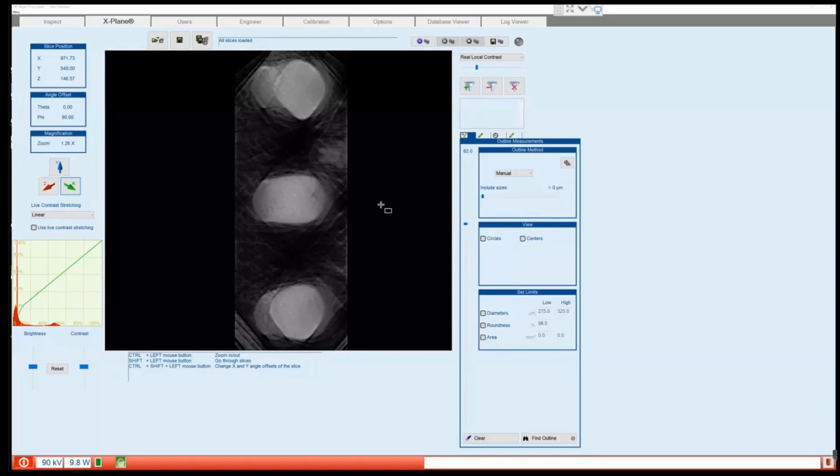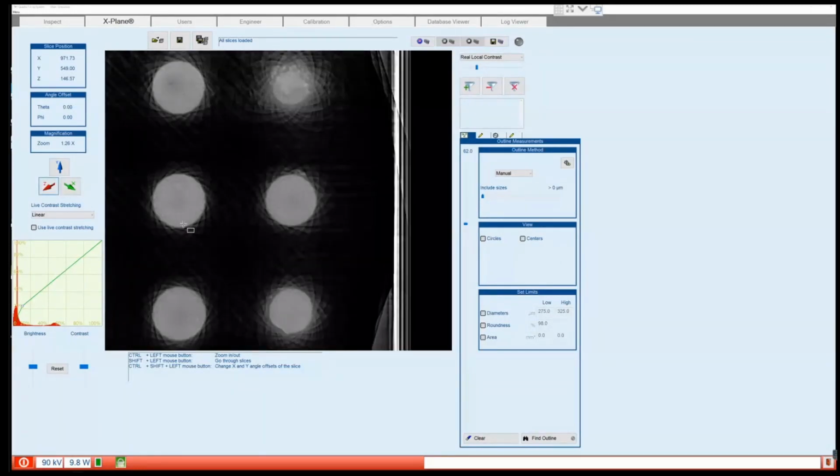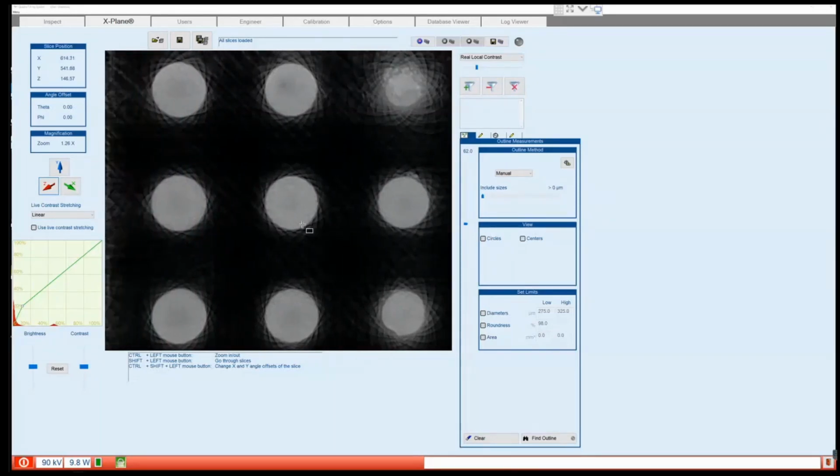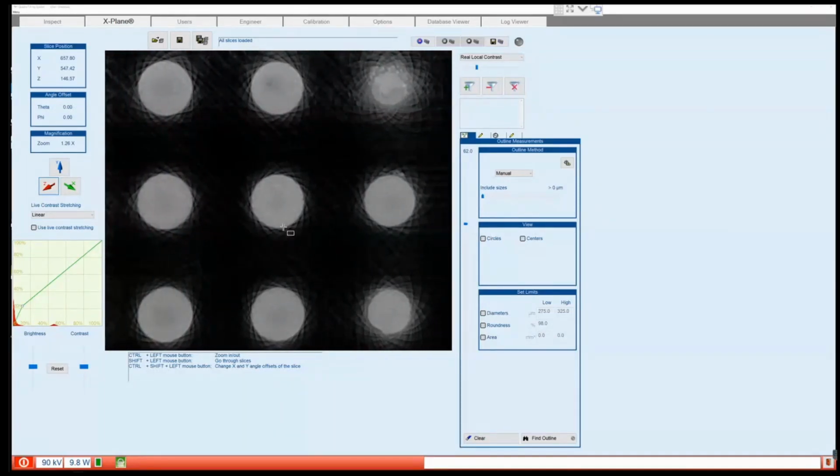So that's how I would recommend setting up a high angle scan. The precision is in setting up the height very accurately, applying a good filter, and choosing the right angle. Again, a 90-second scan, and results are good. Good enough to be able to analyze for defects.